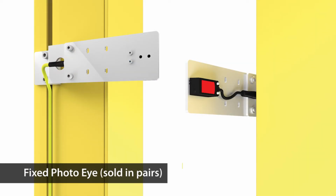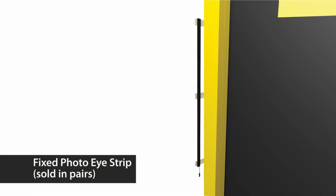The fixed photo eye is a single-through beam sensor. Breaking the beam triggers a door stop or reverse. The fixed photo eye strip is a 1-meter strip of sensors functioning similar to the fixed photo eye, but over a greater area of the opening.